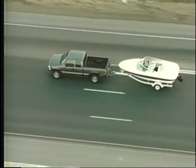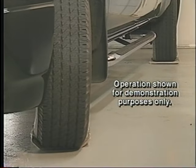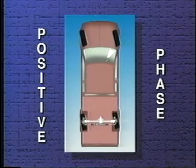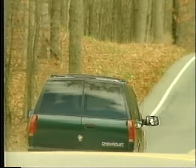The rear wheel steering system helps improve stability during high-speed lane changes. With the mode select switch in the four-wheel steer position, front and rear wheels turn in the same direction during high-speed maneuvers, such as lane changes. When both the front and rear wheels turn in the same direction, the system is operating in a positive phase. Positive phase rear wheel steering improves stability during higher speed maneuvers.